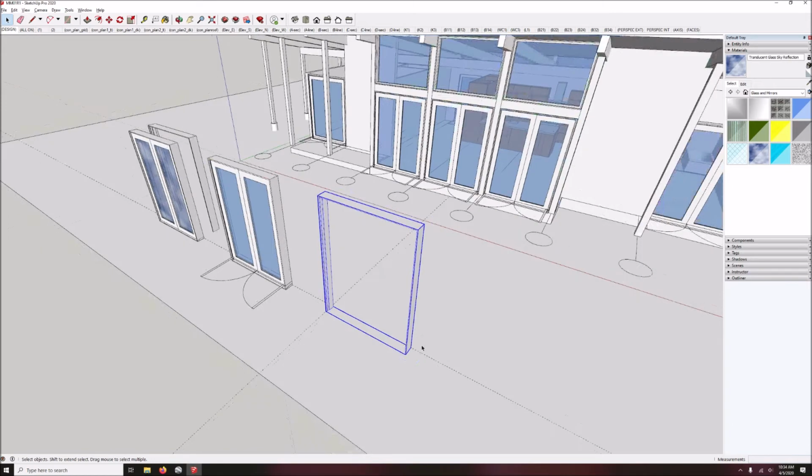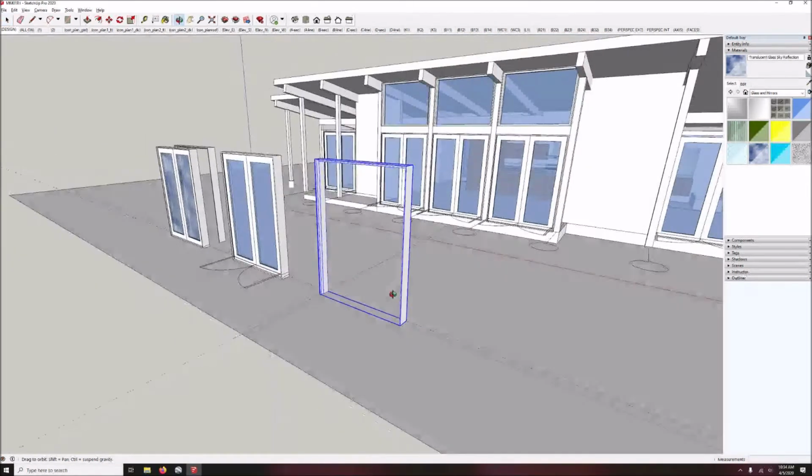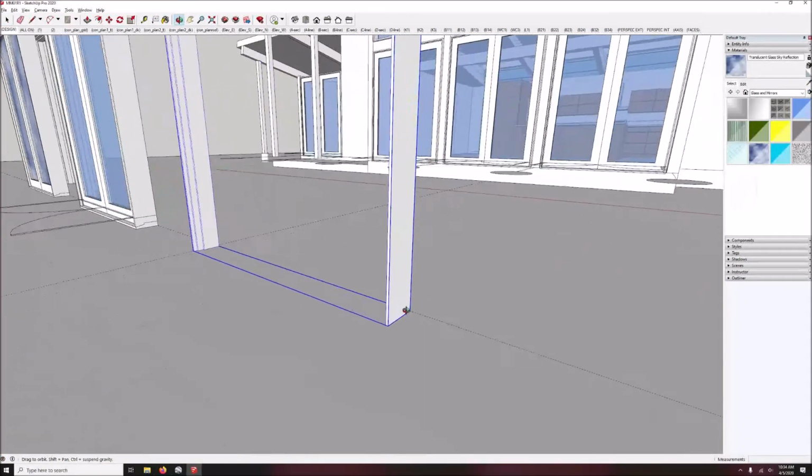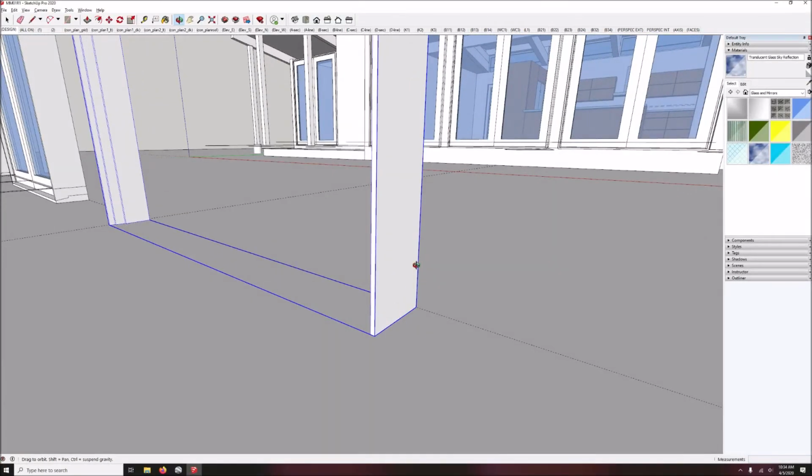Next thing I'm going to do is draw the sill. So let's come down here, and we'll use this face as a convenient surface to draw on. I'm going to start with another rectangle, R for rectangle, click on one corner, pull it, and type in the dimensions I want, 1 3/4 inches by 7.5 inches. Got that right, good. Make a group out of that. Right click, make group, right click, edit group.